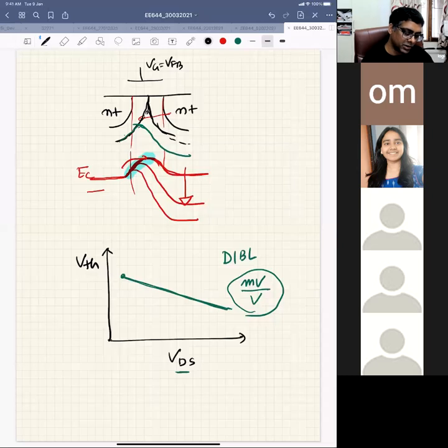If you increase the doping in this channel region, or you increase halo, all those design changes you have to do. You have to increase the surface doping, introduce halo doping and all those things.